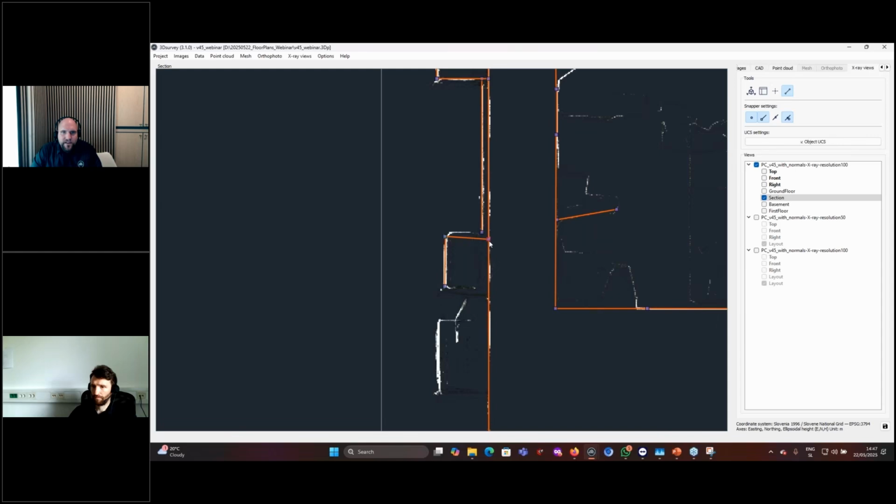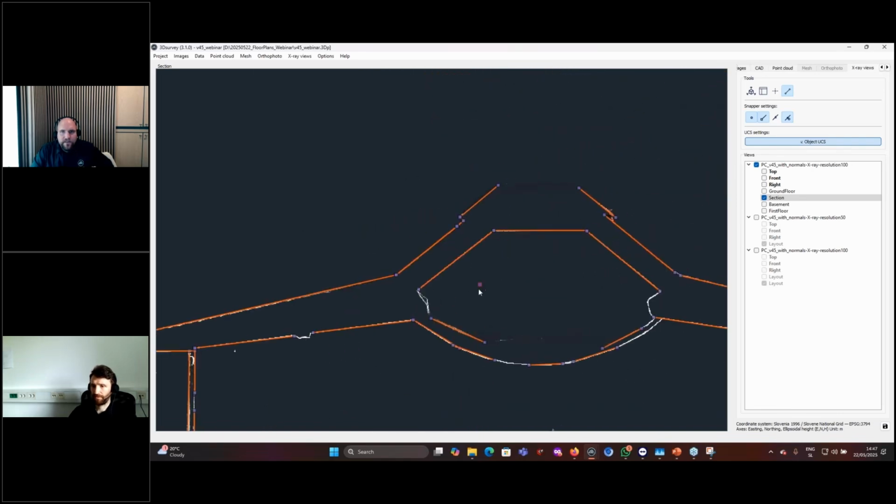In here, I can go and now I'm snapping on this wall. Actually, I want this line to be straight. I can just press F8 or here object UCS, but a lot better, you just press F8 and the line jumps like that. And now I made, you see, straight lines exactly to the wall like that. Perfect.